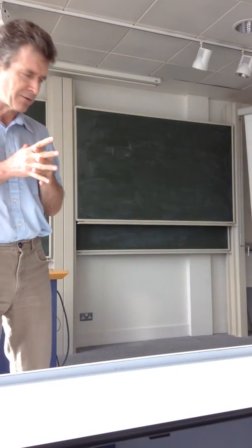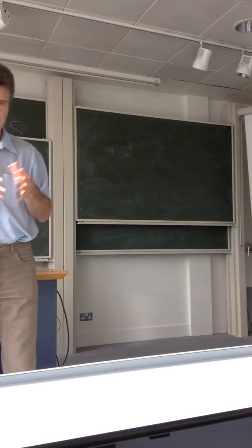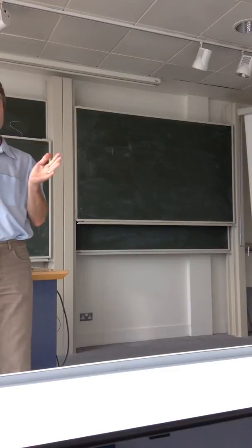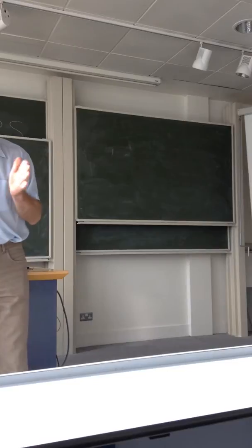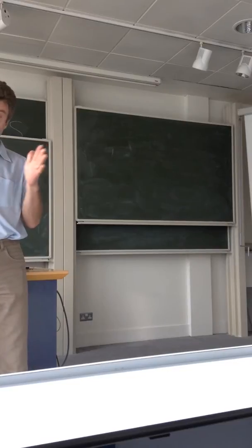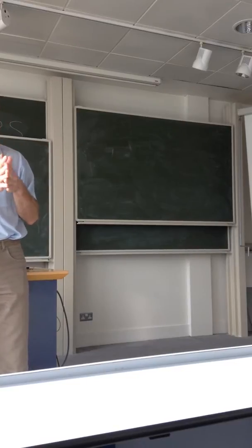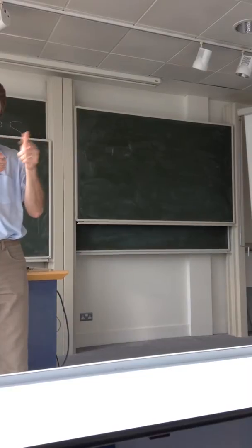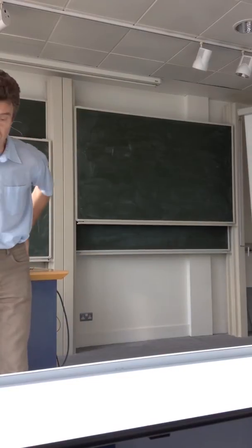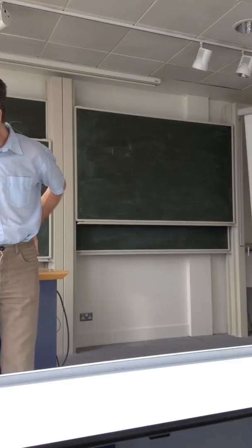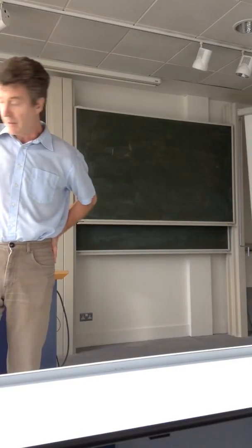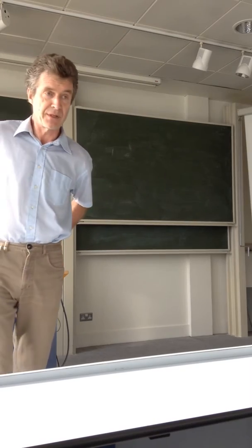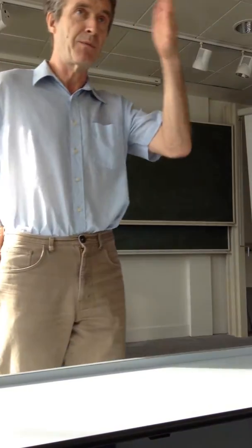The issues about the semi-empirical treatment of the temperature drop across the gap, albeit it's not a physical gap. The cladding could well be in mechanical contact pushing against the pellet, but there's still a bit of a temperature jump there because it's obviously pointwise contact of two rough surfaces with a gas filling. Then the temperature drop through the cladding, and the final one, the temperature drop through the boundary layer on the fluid side. So we derived all of that.